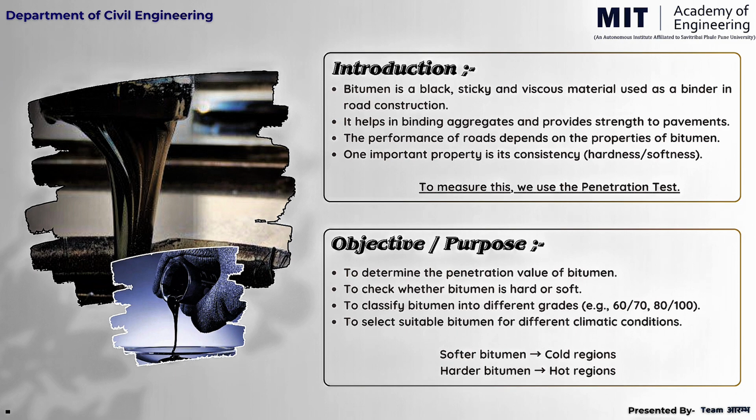The performance of a road mainly depends on the properties of bitumen. One important property is consistency, that is hardness or softness. To measure this property, we use the penetration test.